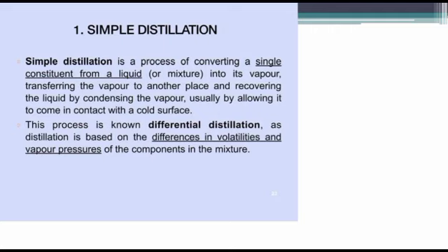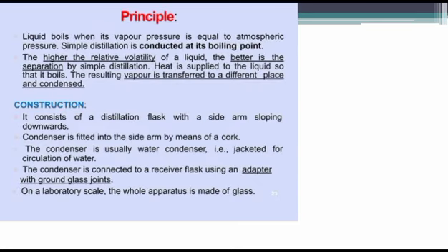a vapor, transferring the vapor to another place and recovering the liquid by condensing the vapor, usually by allowing it to come in contact with a cold surface. This process is known as differential distillation, as distillation is based on the differences in volatility and vapor pressure of the components in a mixture. Principle: a liquid boils when its vapor pressure is equal to atmospheric pressure. Simple distillation is conducted at its boiling point.